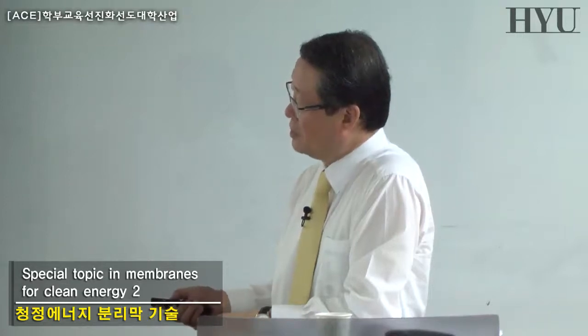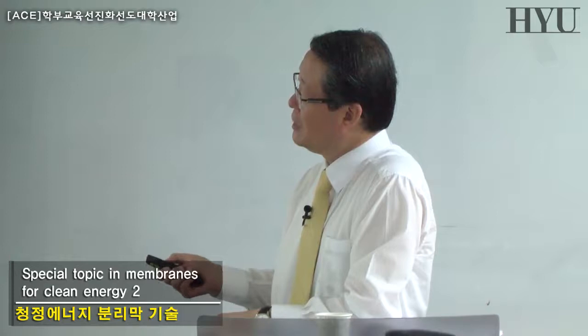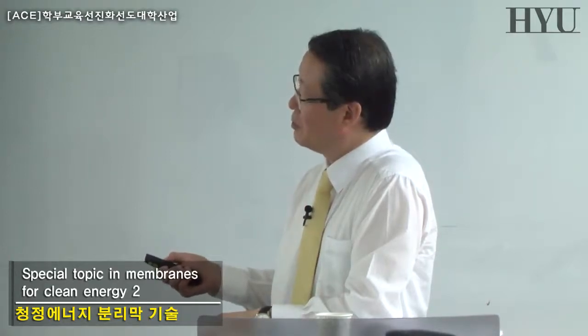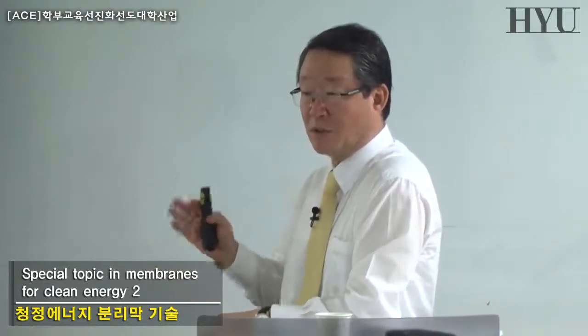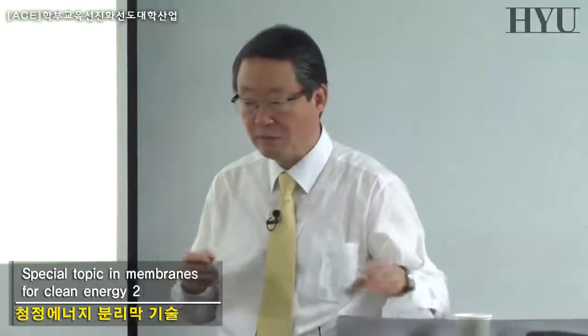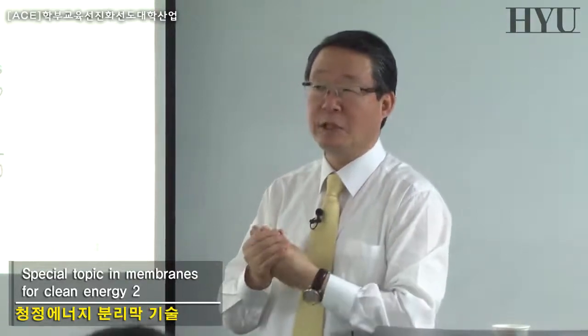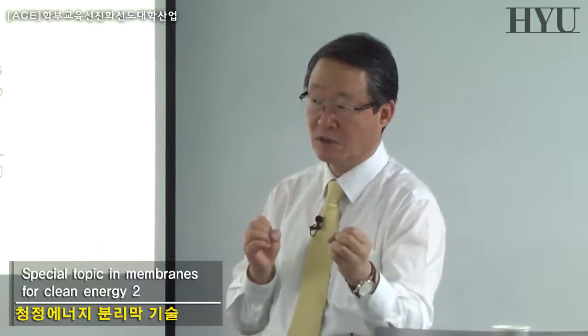So the flux depended upon pressure, and so on. But this L is independent of the pressure. So L is independent of the pressure, whereas the flux depends upon the pressure that you apply. So this LP is the parameter which is an intrinsic property of the membrane itself, whereas the flux is not.